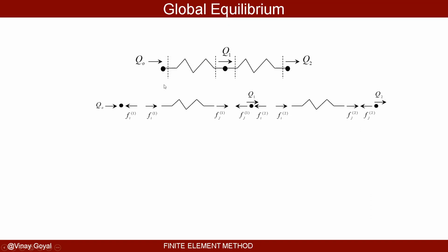So when I do a little cut here, what I have is that at that node, I have Q0 applied, but a force has to be reacting that. So I'm calling that Fi1. And these two forces have to be in equilibrium with each other to get zero. This is an internal force. So that has to go to zero here and has to somehow add up to Q0. When I do a cut here, I get that's FJ1, that's element number 1. And remember, I is the nodal label. Don't get confused. It could be 1, 2, whatever you want. But I called it I so we don't confuse it with this 1. For element 1, that node is I, and that node is J. And so what I've done is showing that element, I cut it here, and internally, that force has to be in equilibrium. Fj1 has to be equal and opposite from this force, Fj1.